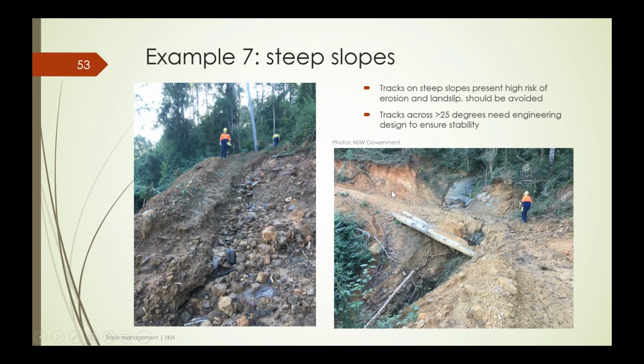We need to have protection of both cut and fill batters, constructed drainage to handle any small catchments running across the road. But you can see here in a poorly done job, the risk of erosion, the risk of slumping is huge, and the risk of pollution in the watercourse is almost a foregone conclusion.